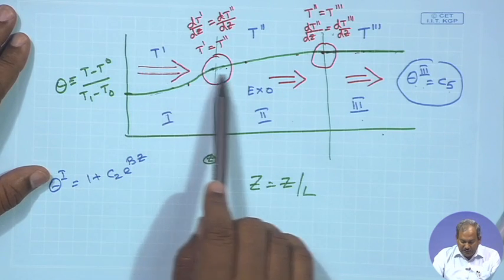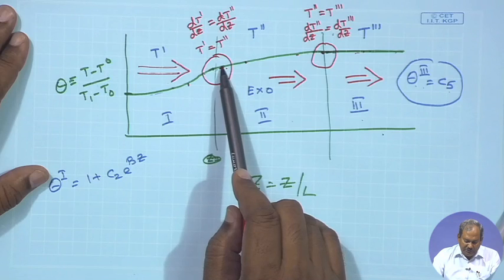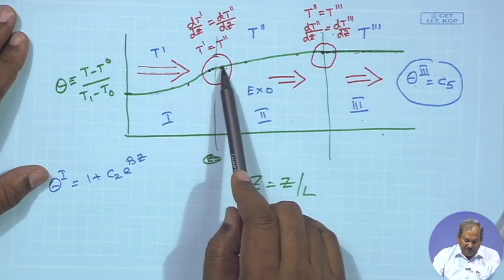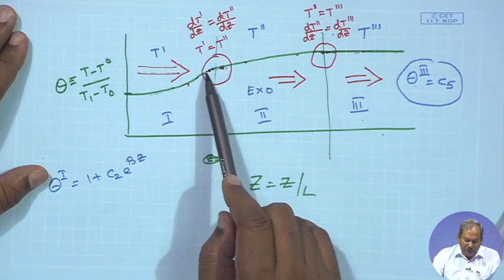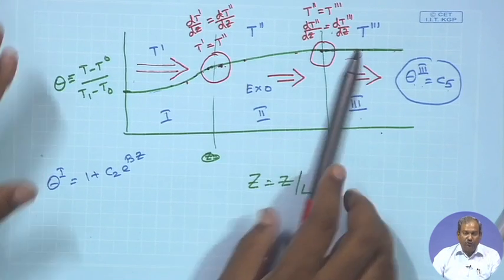The convection is from left to right, but due to the difference in temperature, since an exothermic reaction is taking place over here, the temperature at this point must be greater than the temperature at this point, and whenever there is a temperature difference, there would be a conductive flow of heat which you cannot stop. So, the entering reactants are going to be preheated due to the exothermic nature of the reaction which starts at zone 2.